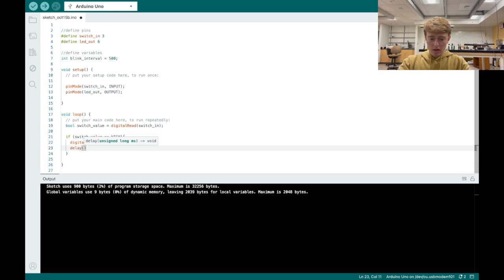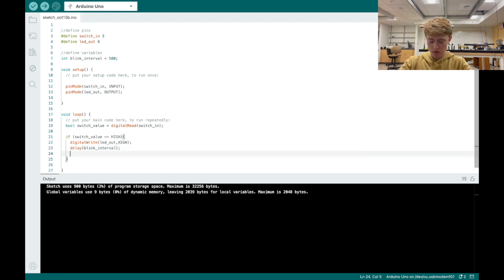So we're gonna delay this so that it stays high for a little bit. We're gonna delay it by whatever the blink interval is. That's what that value is for, okay? So we're gonna create a delay using this function delay, and then we're gonna turn it off, okay? Right now we've got it at 500, that's in milliseconds. So it's on for half a second, okay? So now we're gonna turn it off. After we wait for half a second of it being on, we go LED out, low, semicolon, okay?